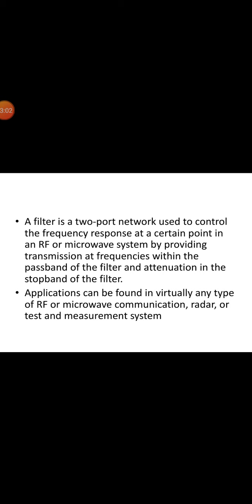Both image parameter and insertion loss methods of filter design lead to circuits using lumped elements, that is, capacitors and inductors. For microwave applications, such designs usually must be modified to employ distributed elements consisting of transmission line sections. The Richards transformation and Kuroda identities provide this step.